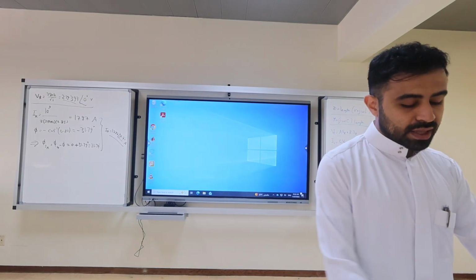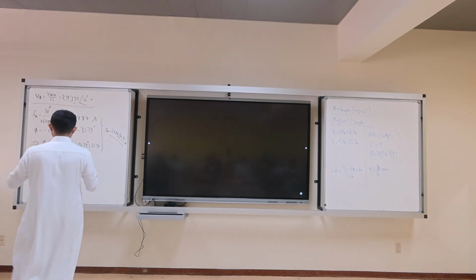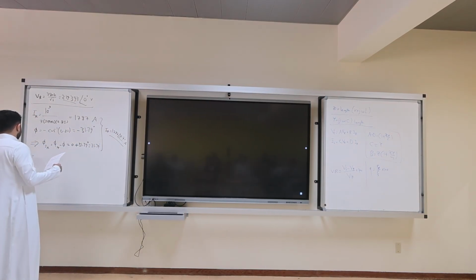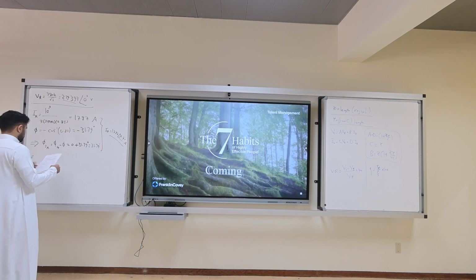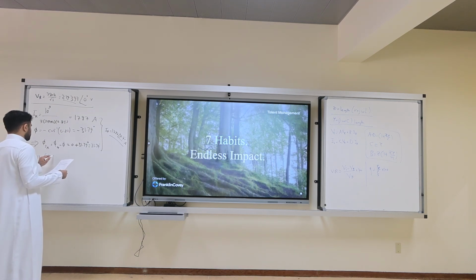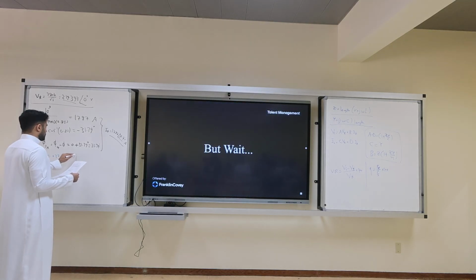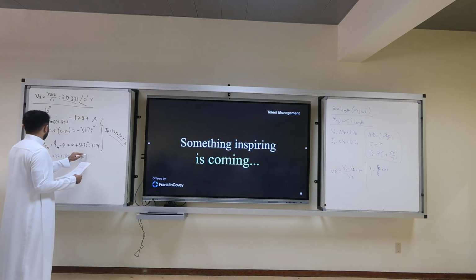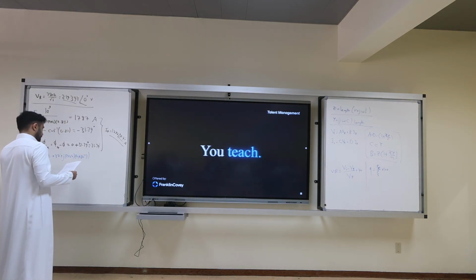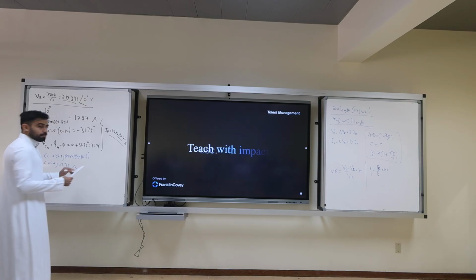Why do you have to calculate the Z and the Y? Because they are to get the ABCD. So what is the Z? Is 180 times 0.037 plus j times 2 pi 60 times 0.91 times 10 to minus 3. You will end up with 6.66 plus j 61.75 ohm.